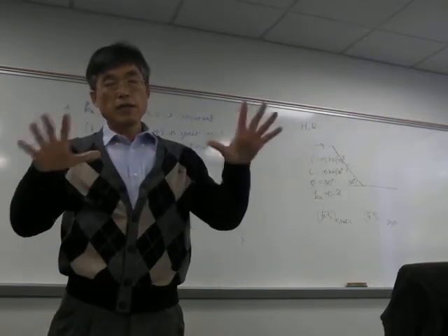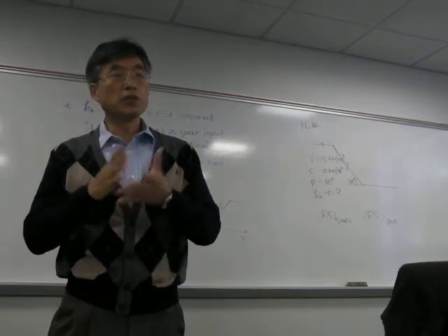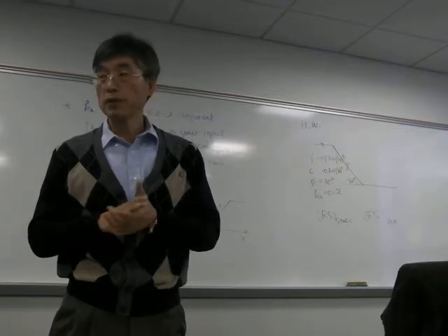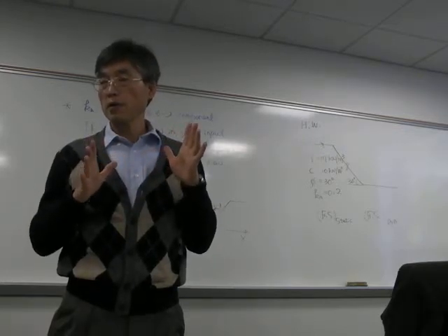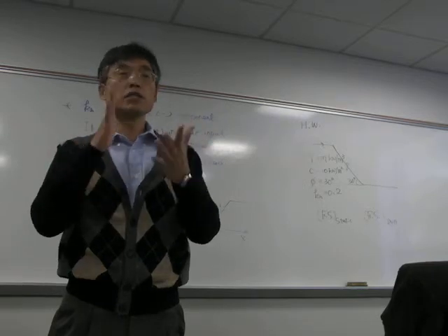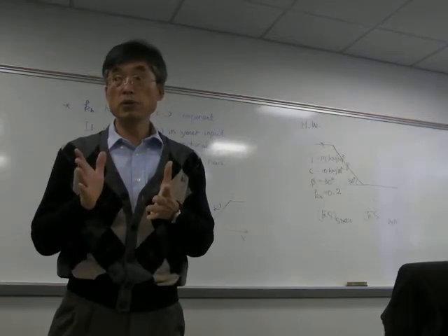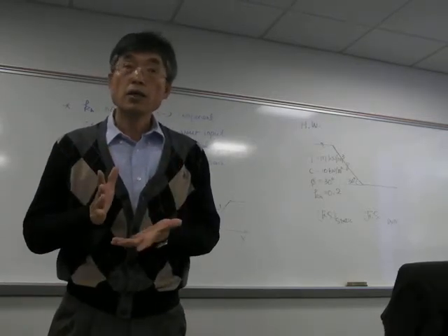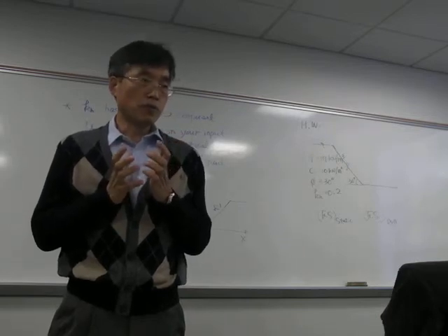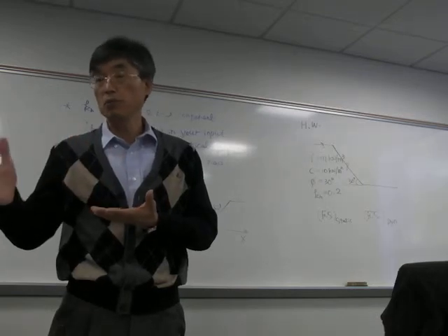Usually, if we just pick one factor of safety for general slopes, I would say somewhere 1.2 or 1.3. So they don't base it on affected area if the dam breaks? If we just pick one factor of safety for whatever slopes, usually it is somewhere 1.2 to 1.3. But let's say this dam is a really important one. Then probably you may want to increase the factor of safety a little bit higher, 1.5.